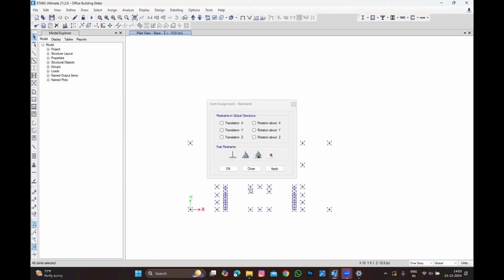So what I'm trying to say is this overturning moment is always very critical when compared to compression, and when compared to direct tension. Direct tension is when someone is lifting you. Overturning moment is when someone is hitting you on the head. When someone is hitting you on the head, the two legs are going to resist the moment. Very important. Okay.